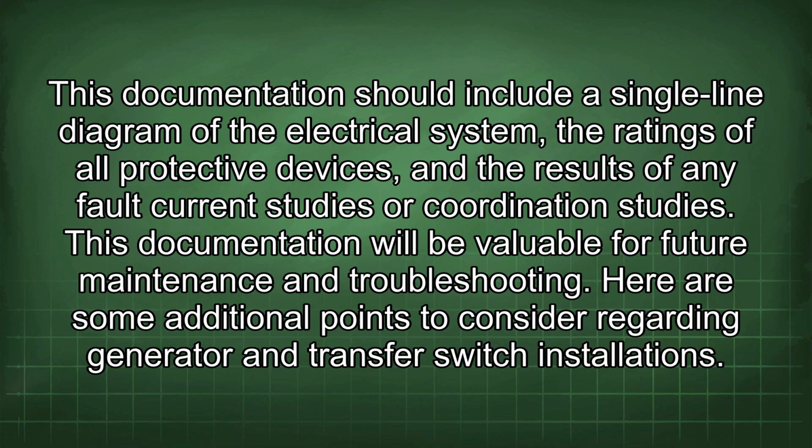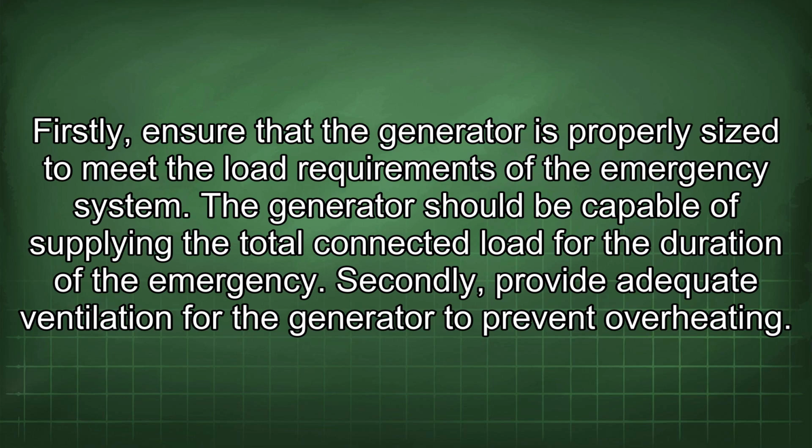Here are some additional points to consider regarding generator and transfer switch installations. Firstly, ensure that the generator is properly sized to meet the load requirements of the emergency system. The generator should be capable of supplying the total connected load for the duration of the emergency. Secondly, provide adequate ventilation for the generator to prevent overheating.